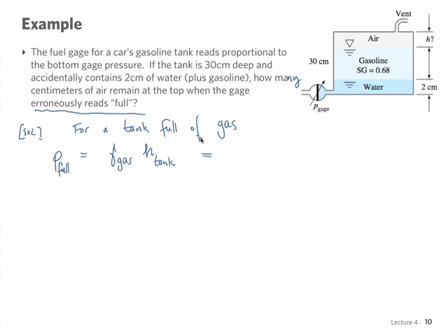And we're going to probably need to choose a density, because you go to a table in your book and you will have the specific weight or the density of water for different temperatures. You can choose 20, 25, something reasonable. And just as long as you put on your solution what temperature you've chosen to solve your problem, all is fine. I have chosen 25, which is not actually standard. Perhaps 20 would be standard, but this is what I decided to use when I was solving the problem.